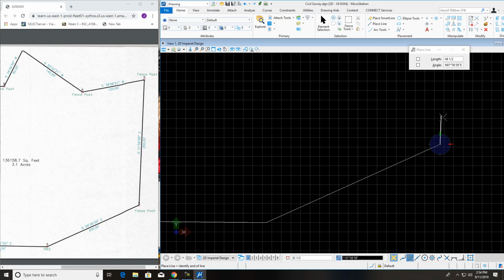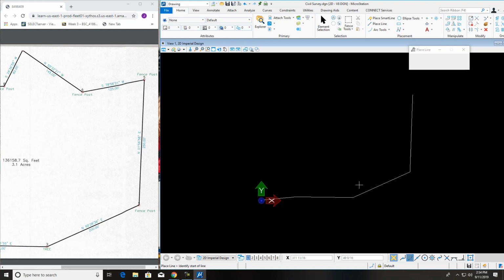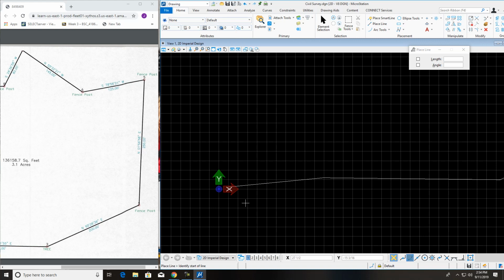And when I move this, you see the length of it is moving. We could change it up here, or you can hit the tab button, go back there, hit 250 and click with your left mouse button. And then T would turn it around where it's straightened up. So you guys kind of get an idea of how that works. And just for sake of time, I'll show you some more stuff here.